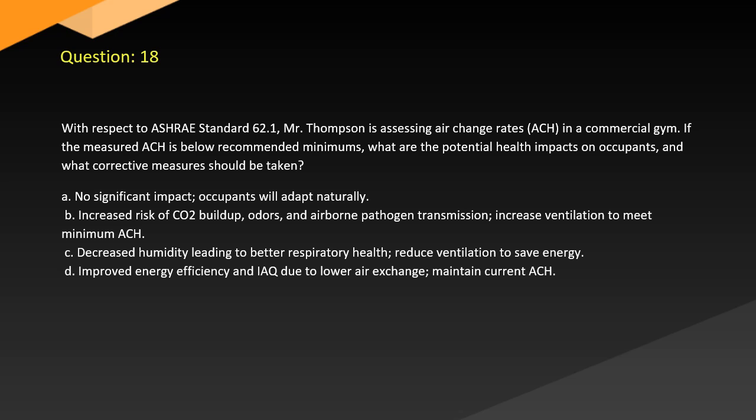B. Increased risk of CO2 buildup, odors, and airborne pathogen transmission. Increase ventilation to meet minimum. C. Decreased humidity leading to better respiratory health. Reduce ventilation to save energy. D. Improved energy efficiency and IAQ due to lower air exchange, and maintain current rate.